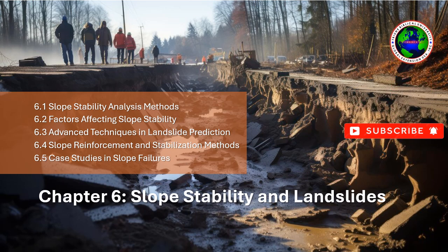Ground-penetrating radar, GPR. GPR is a non-invasive technique that uses electromagnetic waves to image the subsurface. GPR can be used to detect changes in soil properties, identify fractures, and locate voids or weak zones within a slope that could lead to instability.